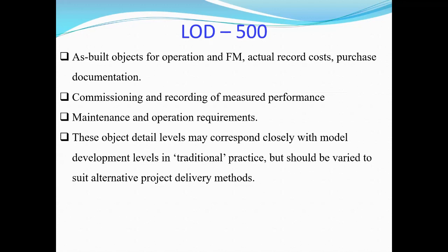Otherwise, you have to go to the site and do a site investigation, which may not be accurate. You have to test the rebar, test the concrete strength, and so on. It is costly and may not be accurate. But if you have the information on the building owner's side, then you can easily use that. That's the purpose of LOD 500 models.